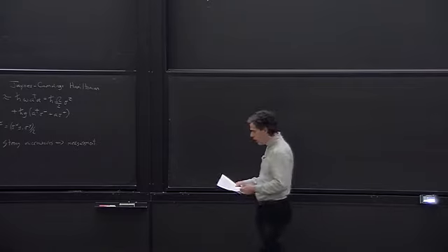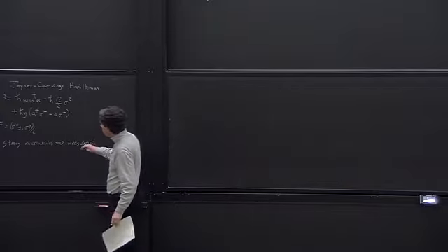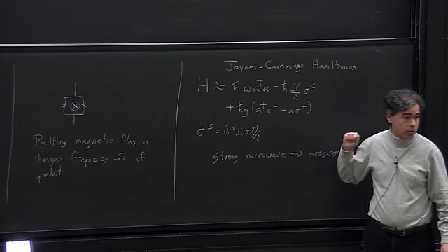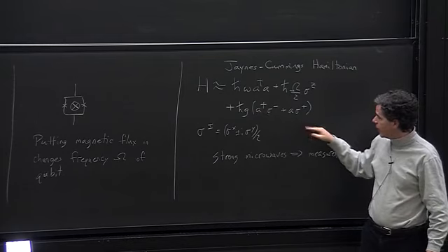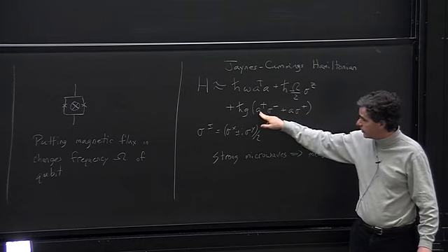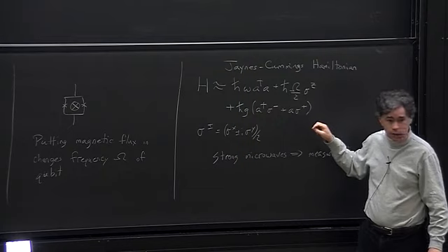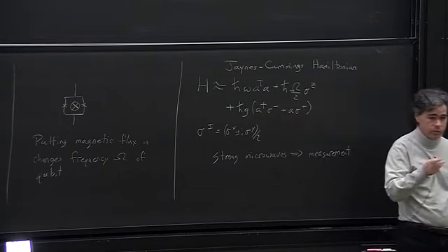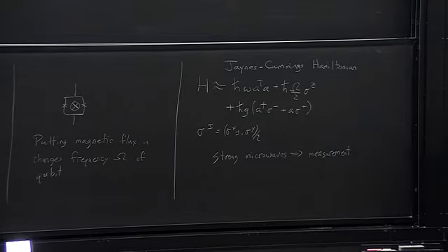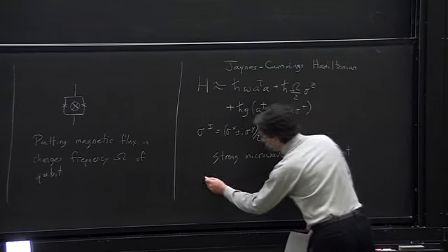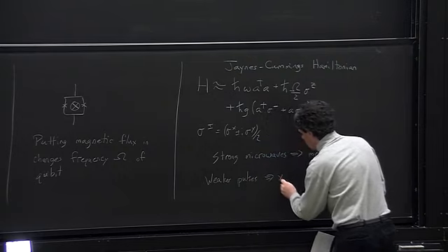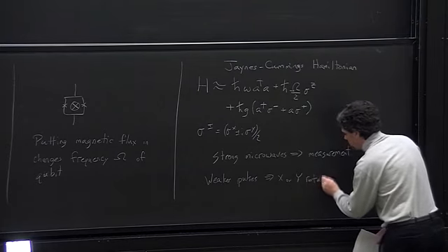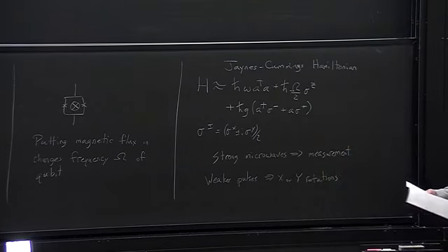OK. So the other thing you can do is you can inject not really strong microwaves, but much weaker microwaves. And again, it depends on what your coupling strength is here. But that lets you do some deliberate A and A daggers, which then causes the superconducting circuit part to transition from ground to excited. And that lets you do your X and Y gates. So there are weaker pulses. OK?